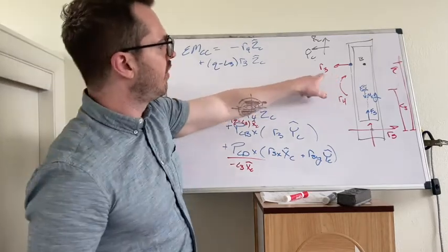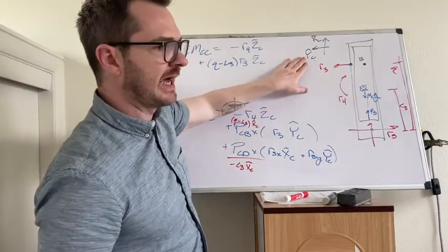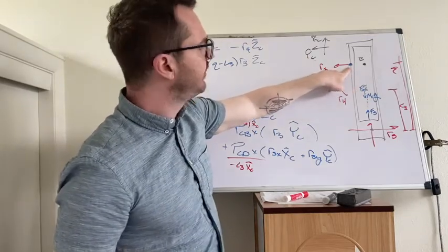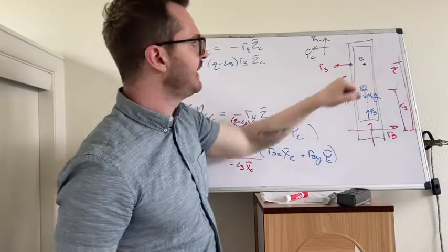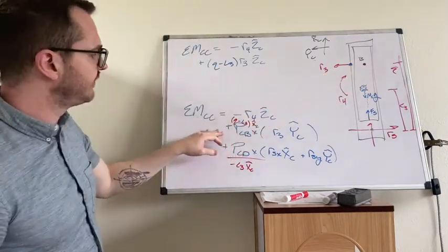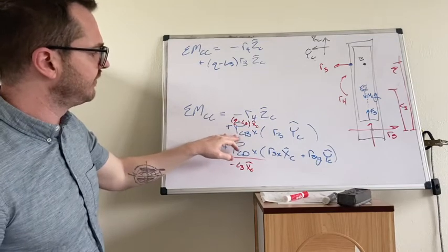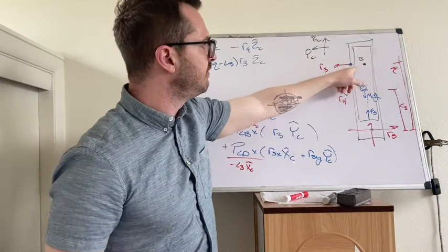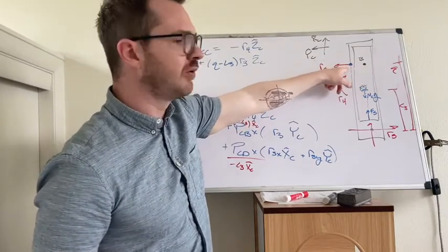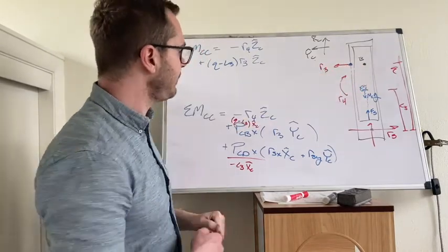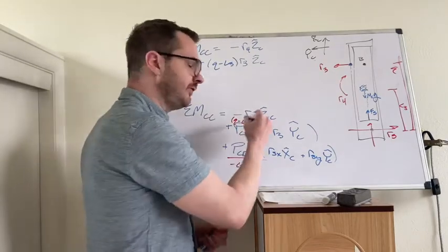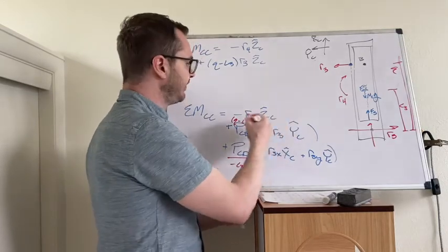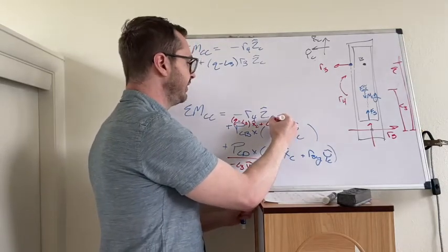If you look at R3, we know which direction it acts in. It acts in YC. Look at where we attached it. We could attach it here at this blue point. We could attach it here at point B. I did the position vector from C to B. What if we had done the position vector from C to B and B over here to this point on the side? That would have added some component, I'm just going to say L, some component in the YC direction, right?